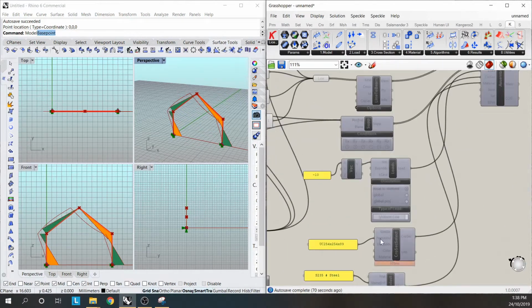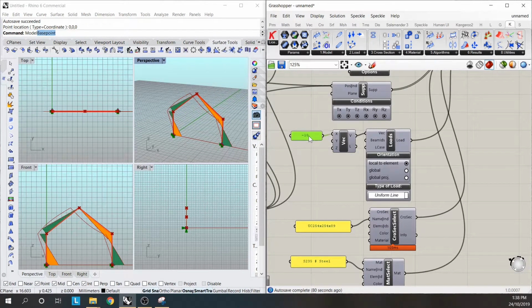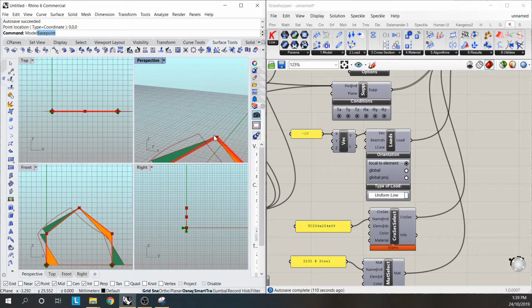In the normal case, and you'd need to refine this more, you would add, say, a big load on this face, roof loads which may vary based on the distance from the edge of the building, and you can do that with beam IDs here. So you can give each element a different load, or you could split this element up into multiple elements to give it different loads at different locations. Then you wouldn't see a 0 moment at that peak.